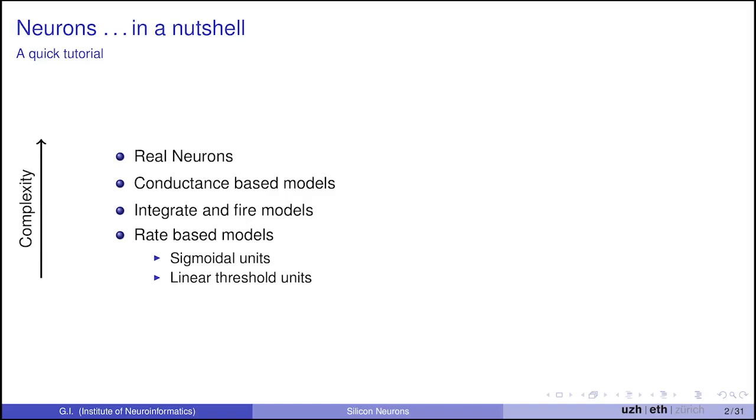So it's still a complex device because it has a nonlinearity, this max between a threshold and the output. But it's very simple, and you could even do it with a simple current mirror. So if you want to do linear threshold units using analog circuits, all you need is a single or maybe 2 transistors to do the neuron functionality.